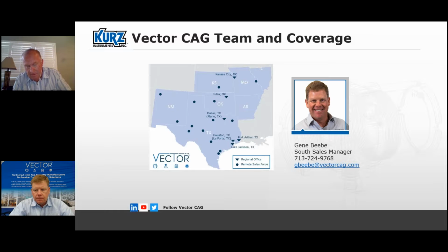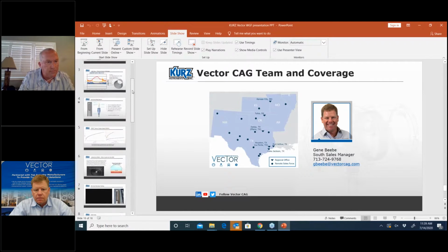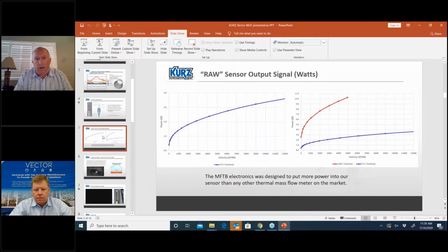We do have time. The first question would be, is the higher sensor temperature safe for use in hazardous environments? Okay, absolutely. In fact, this is really the same circuit as our standard sensor. We're simply operating it a little differently. So for explosive environments, we have a power limit on our probe of about 12 watts. So we only allow up to 12 watts of power.